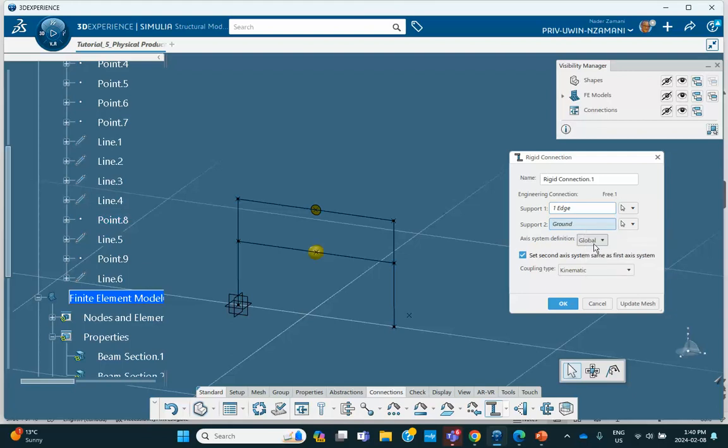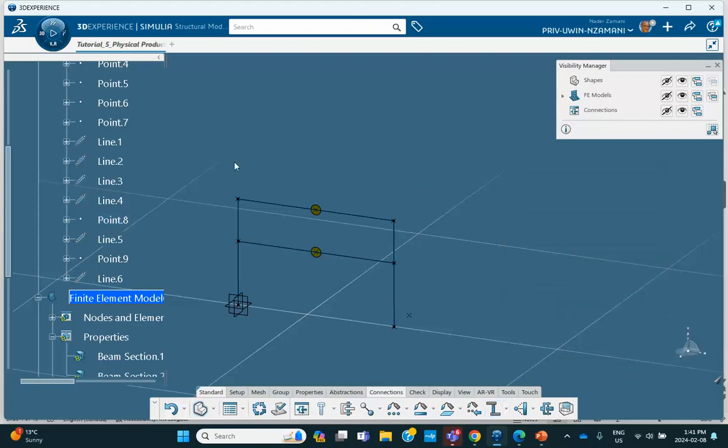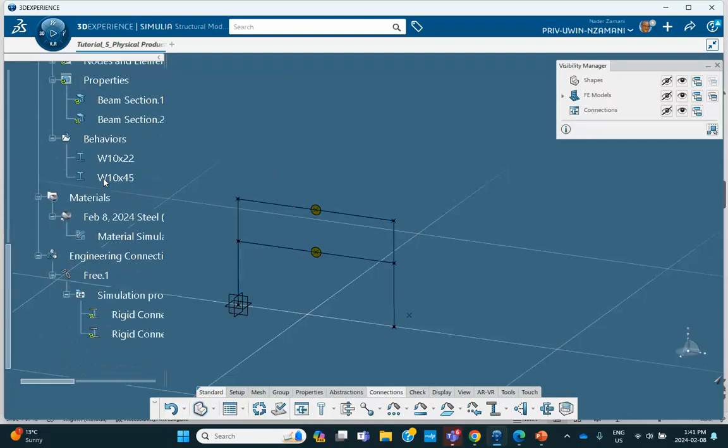Remove all, and this is going to be there. Okay. Now, the other one would have been fine too, but because that vertex that I picked was actually 0.8, we say fine. Good. Now we're going to place our lumped masses at these two locations.